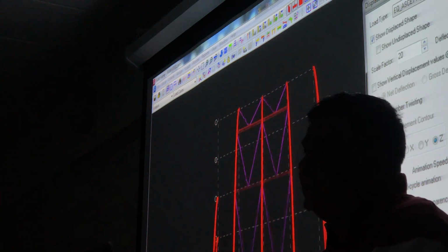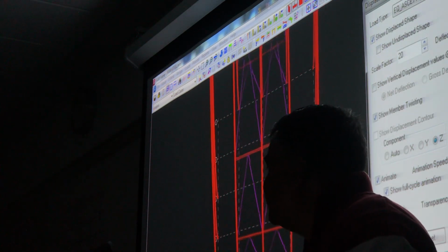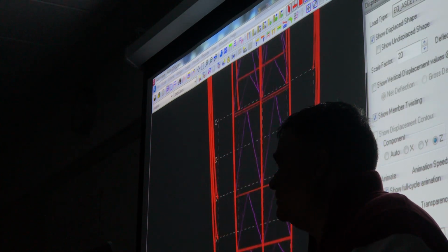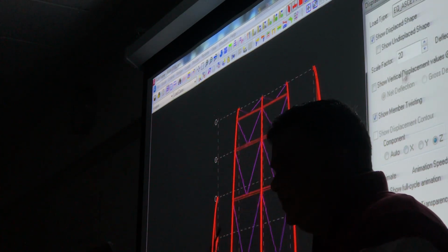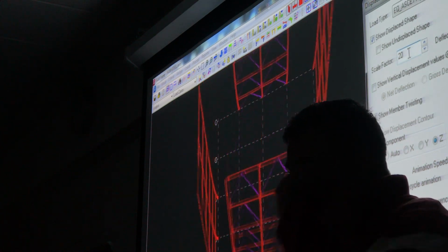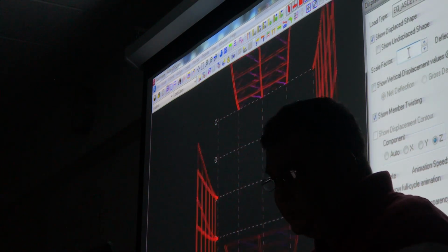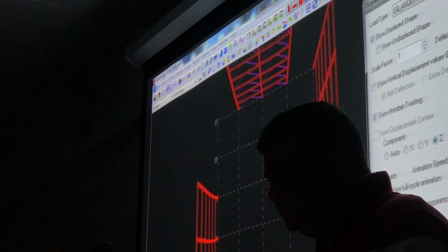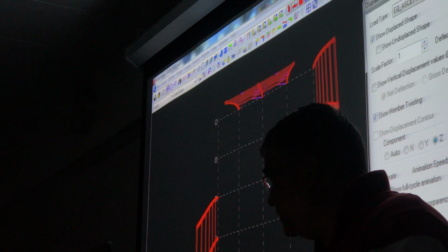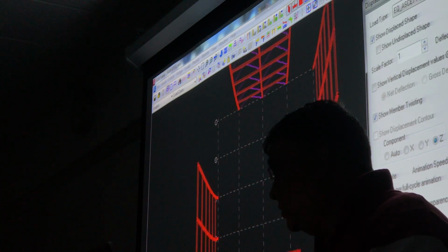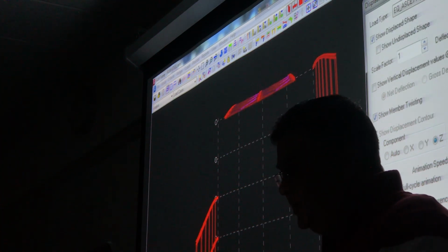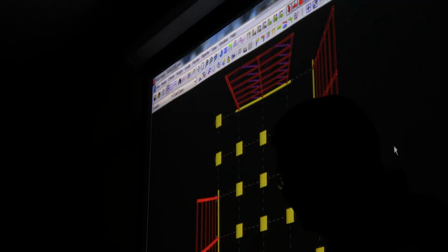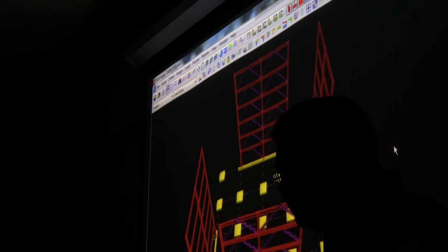The reason is, other direction is moment frame. Moment frame is very flexible compared to base frame. That's normal, I've seen a building do that. No, it's not. Honestly, it's too much because I'm scaling it to 20 times. This is how the building will behave in real. Still a lot. It's like going like 20 feet, if that's right. No, yeah, your moment frames are not enough.